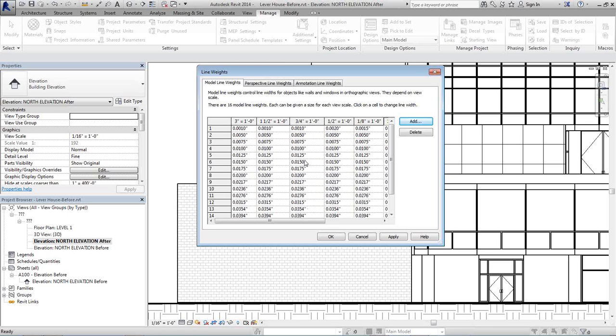And that's a good point to make. Just because you can add line weight scale settings doesn't necessarily mean that these are the right numbers, the right thicknesses for that scale. So what I normally advocate for is that you should test these line weights for the scale you're working in, which sounds arduous, but most firms and offices are really working in maybe 6 to 10 different scales. So arguably you do it once and you're all set.